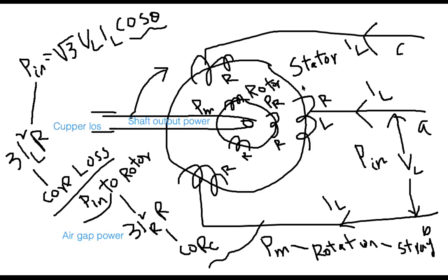Input power to the stator is my start point; subtract stator copper losses and its core losses, then the difference is the input power, or air gap power, to the rotor. Again, subtract its copper losses and its core losses. That is the mechanical power on the shaft. By then the motor has started rotating, so subtract the rotational losses and stray loss or any miscellaneous loss. That is my shaft output power.